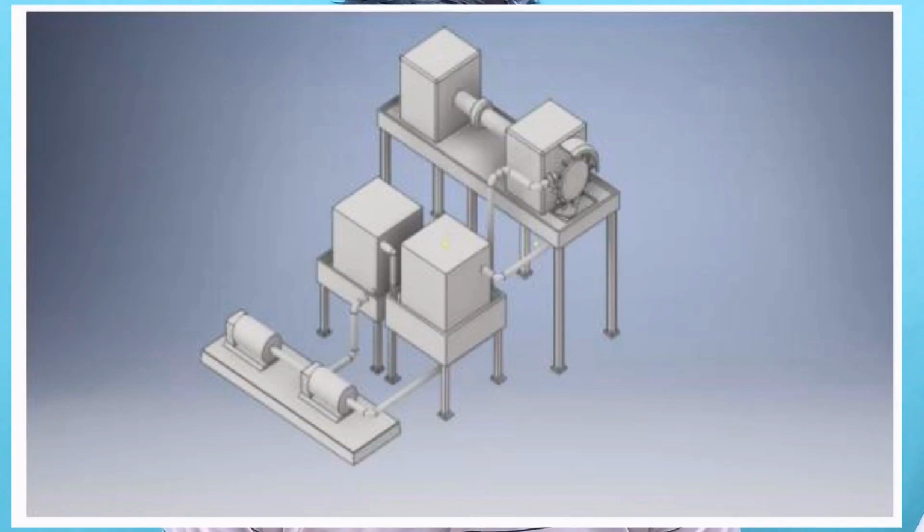Now let me talk about the working of a Pelton turbine. Before that, let me discuss some basic things of the Pelton turbine. A Pelton wheel is an impulse turbine that has at least one free jet. This jet releases water into aerated space where it is caught by a series of buckets. I have explained in the previous part what a bucket is. A bucket is basically a blade. Buckets or cups are located on the runner, the rotating piece of the turbine that is used to convert the water energy into mechanical energy.